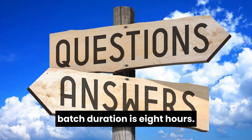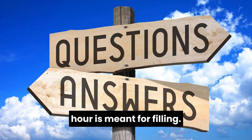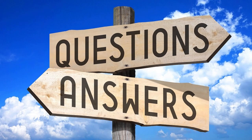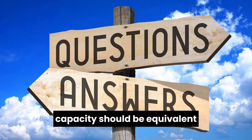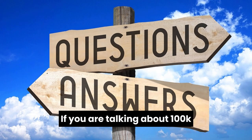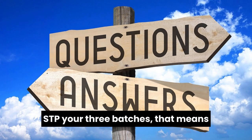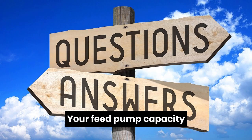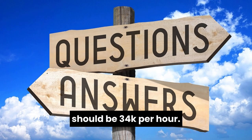Batch duration is 8 hours. In these 8 hours, 1 hour is meant for filling. That means your feed pump capacity should be equivalent to your batch volume. If you're talking about a 100 KL STP, with 3 batches, the batch volume is 33 or 34 KL. Your feed pump capacity should be 34 KL per hour.